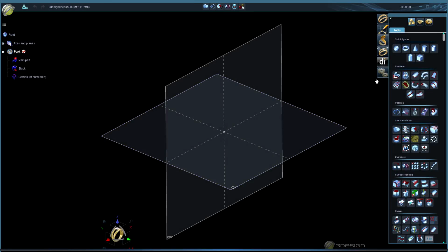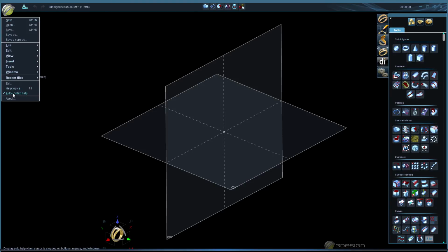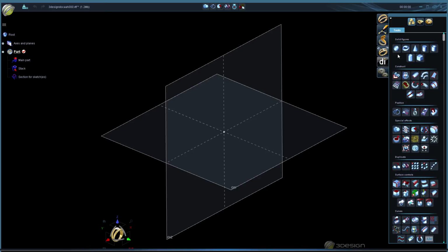Close that. If you don't want that popping up in front of your screen every time you leave your mouse hovering, you can turn off auto context help here. Another thing some people do is delay the help time. You can set that in your F12 options. So if I turn off auto context help, it will no longer pop up by pointing at the object.